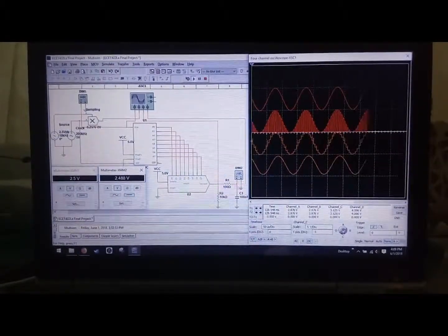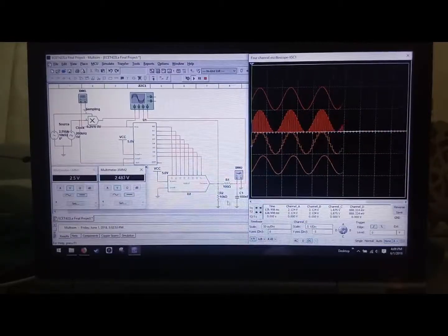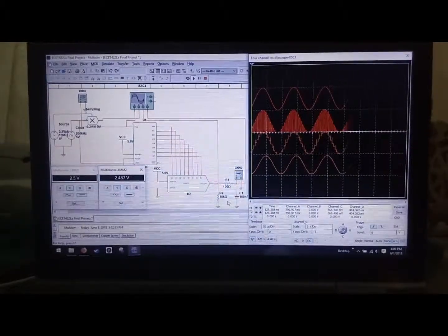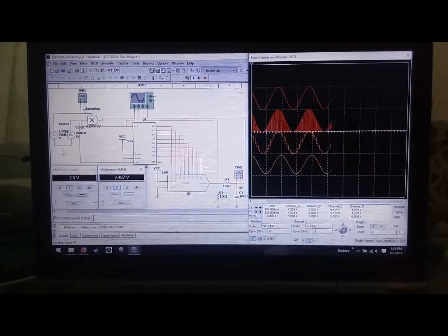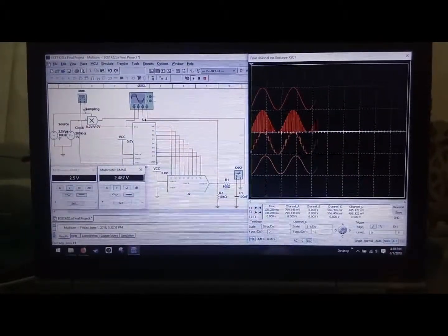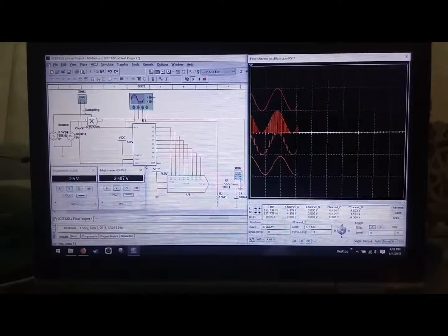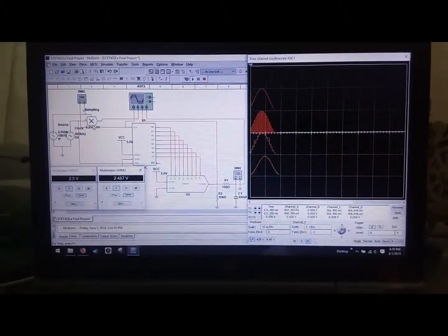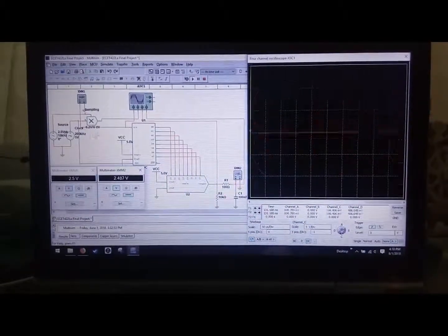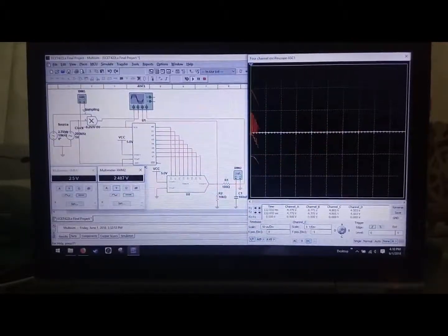In this last part of the circuit, this is what is known as a low-pass filter without a gain configuration. We do not use a gain configuration for this part because we already used a preamplifier in the start of our sampling process.